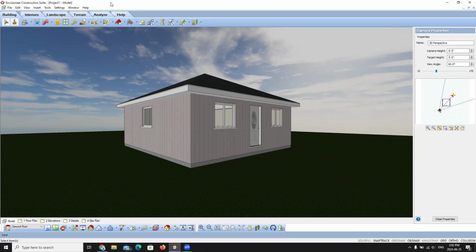results. If you're trying to match an existing finish, you can take a picture of the finish with your camera and then save that image to a computer so that it can be edited. When sourcing your textures, you want them to be in either a JPEG or a PNG format, unless you're creating a transparent image. Then you should be saving that type of texture in a BMP bitmap or in a PNG format. Once you have found the material you want to use, you can then save the material to your textures folder on your hard drive.